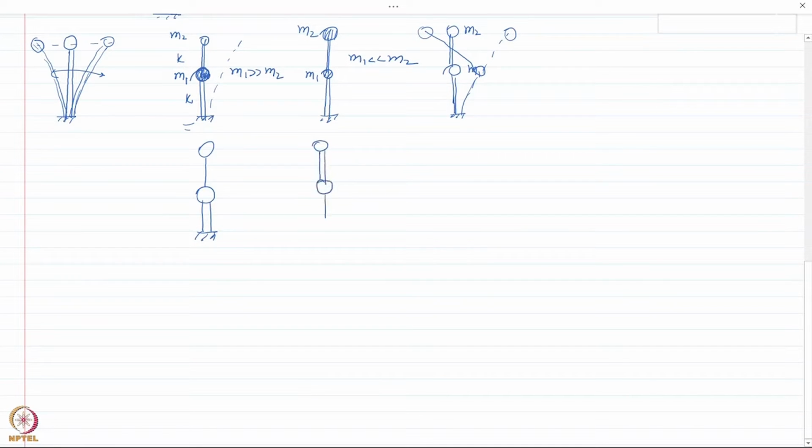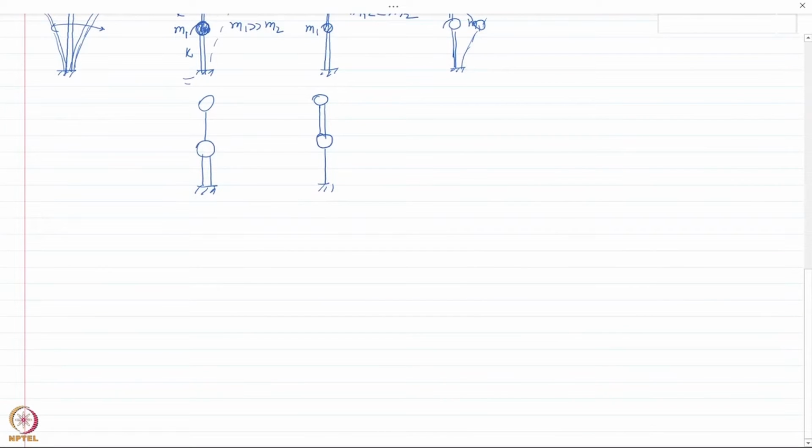And in this case also, we can imagine that depending upon the stiffness between the masses and the support, the overall response is going to change. Now in previous chapters we assumed a deflected shape of a continuous system, which we called a shape function, and utilized that to reduce it to a single degree of freedom system. But that was an approximate method, and we assumed that the deflected shape can be represented by the static deflected shape or some other function.